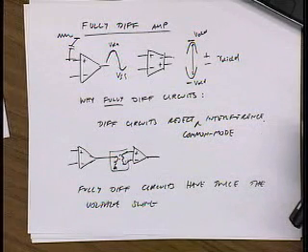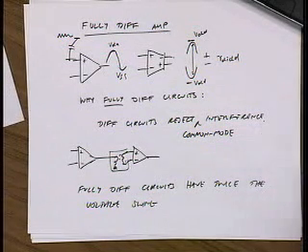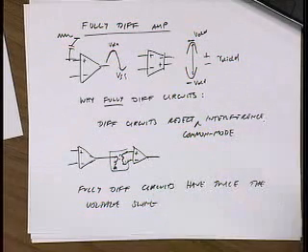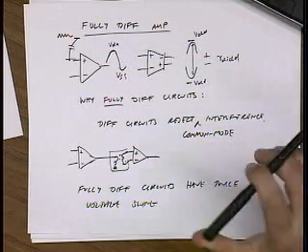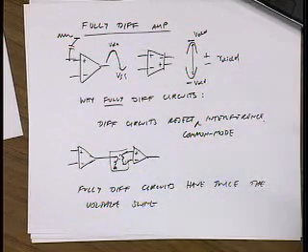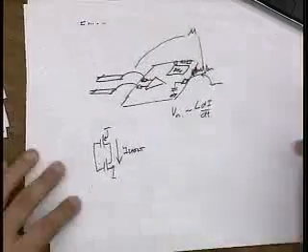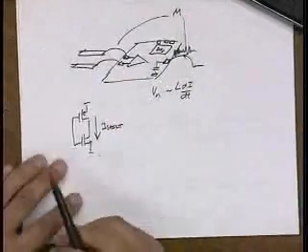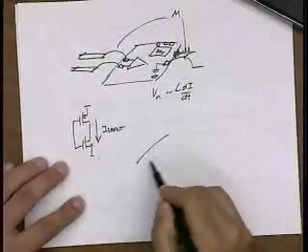Nowadays when you build circuits, it's almost obvious to go differential, especially because you're usually integrating your analog circuits with other things, and you want to get as much noise immunity as possible. Without even thinking too hard, if you go differential, you're going to reject a lot of noise. We talked about the noise pickup in the package, and a few lectures back we talked about the noise pickup in the substrate.